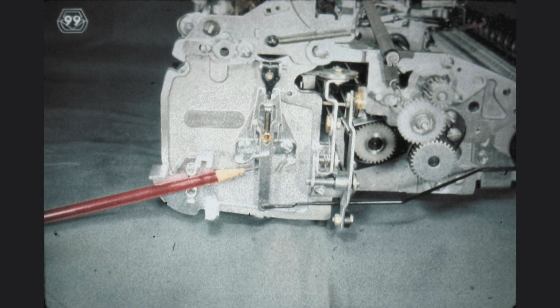We have seen earlier that the angular position of the tabulation stop rack is determined by the indicated tab set and clear angle. If you operate the tab set and tab clear buttons a few times, you will find that the lugs above the pencil are used to limit the motion of the tab set and clear lever. Since this mechanism is totally manual and operated from the keyboard, let us now cover it in its entirety.